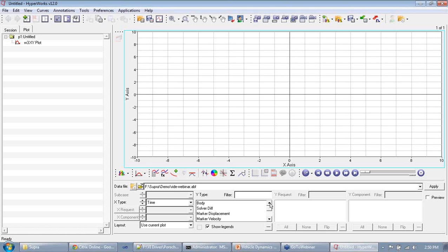To make more sense out of the results for our interest, what I would recommend is remove the ABF extension and replace it by a PLT. This instruction has been documented in the document that is provided, and what this does is it filters only the results that we are interested in and ignores the more general results that we can also plot.